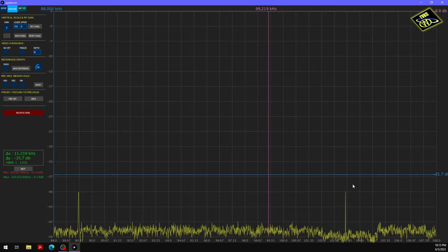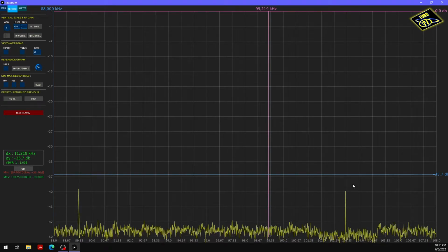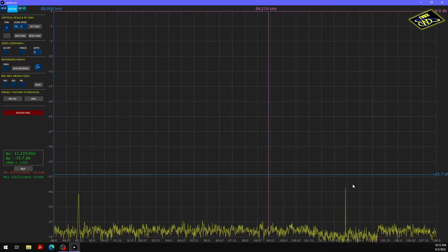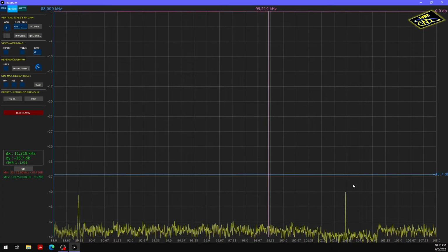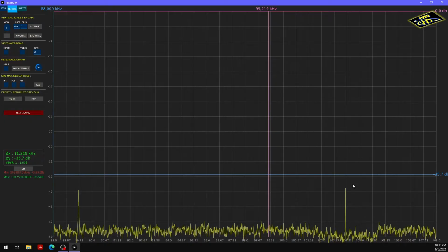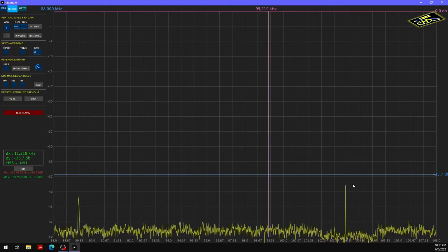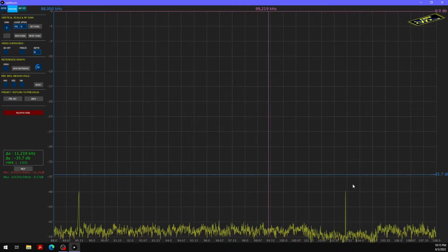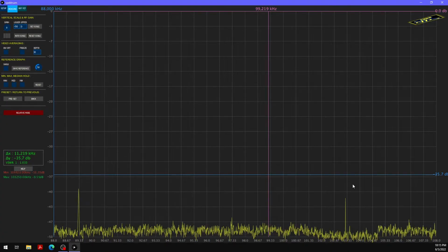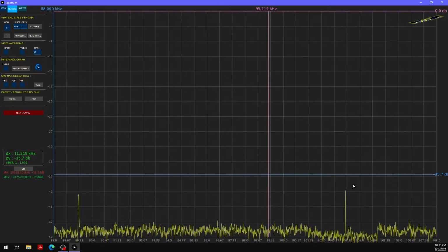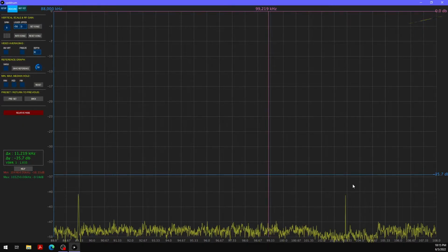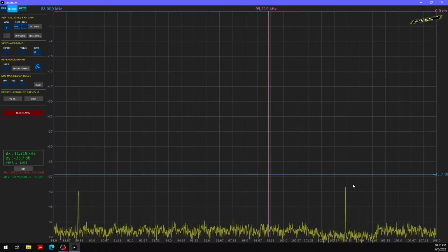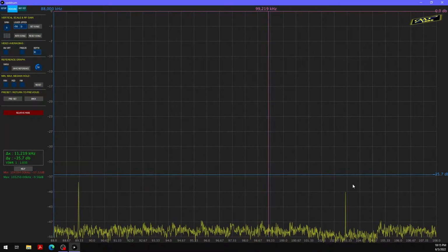And cable companies will often know where these high power transmitters are and avoid using those frequencies on their coaxial lines in areas that they know are very close to the transmitter and would be affected. And a very common thing with the mid split is to actually use the FM band as like a guard band. So they don't use the FM band at all. And the downlink is above the FM band. The uplink is below the FM band.